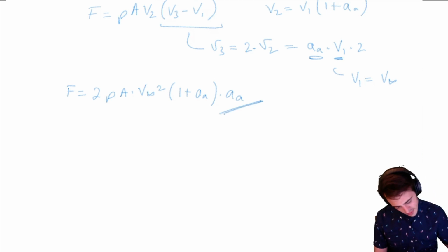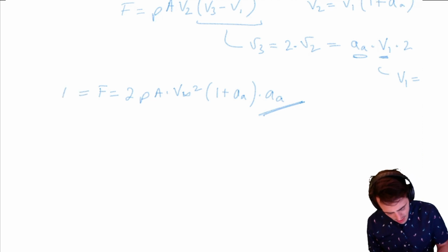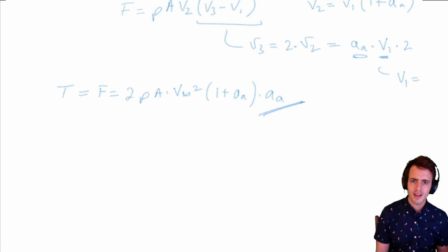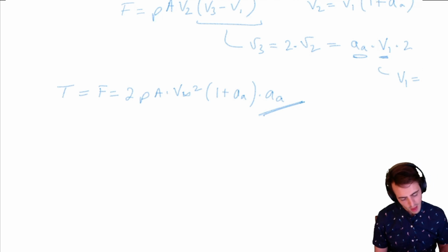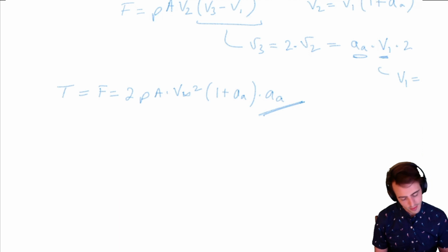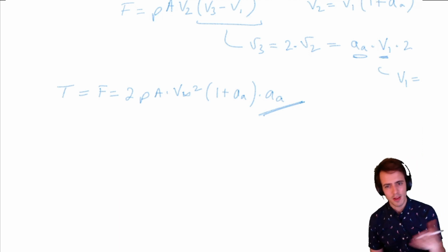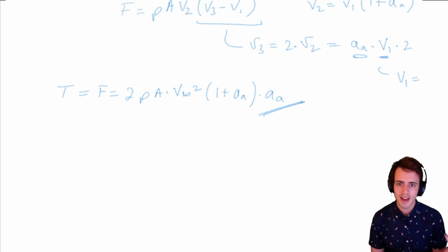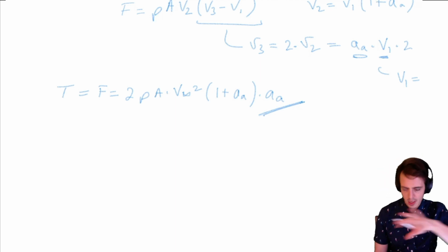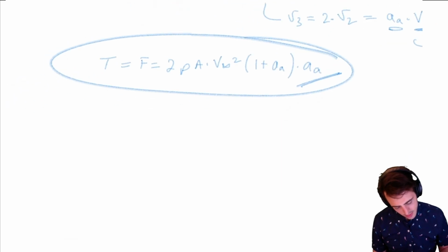So think about what we've got here. As soon as we've got our force, well, this is actually just our thrust. So if we've got our thrust determined, we could then work out what our axial induction factor is. To determine our thrust, we need our axial induction factor. So we're going to look at how we solve that next lecture. Before we get there, we're going to just do the same thing for the torque. So let's just write what we've got here.